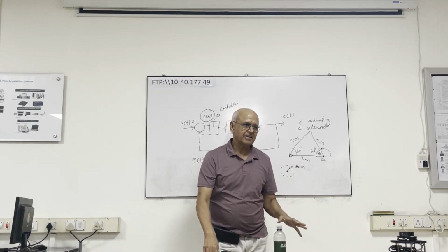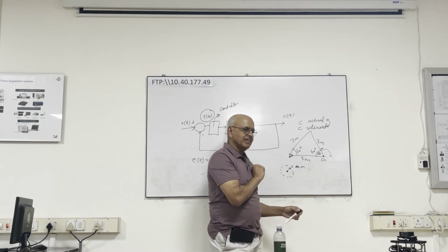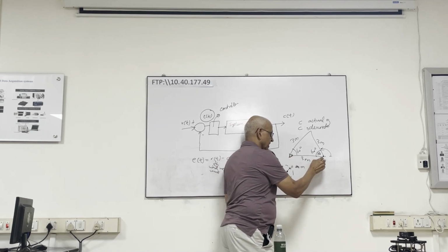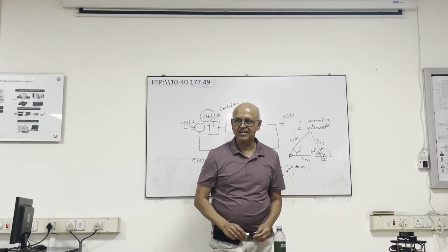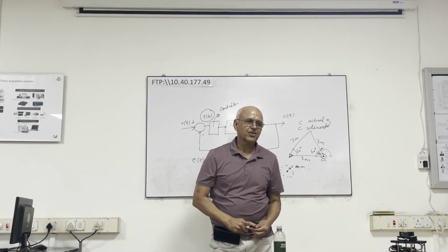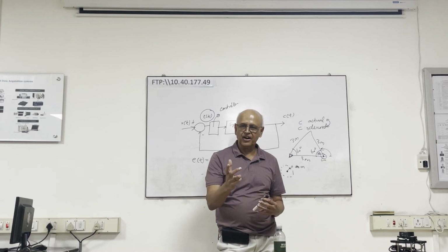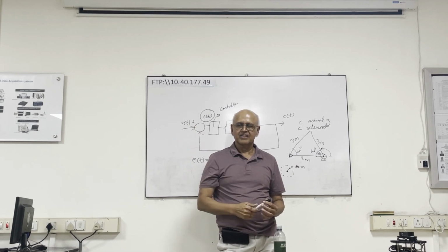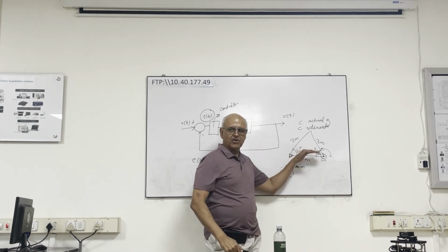And when that happens, what you want to do is, let me back up, I missed a point here. You might not get into the circle, because if the robot veers like this, you're never going to reach that circle. So do you realize when you drive, you have to not only monitor how far you've gone, but you've got to point and drive at a certain target point. That's how we drive, right? So therefore, I have to maintain heading control.